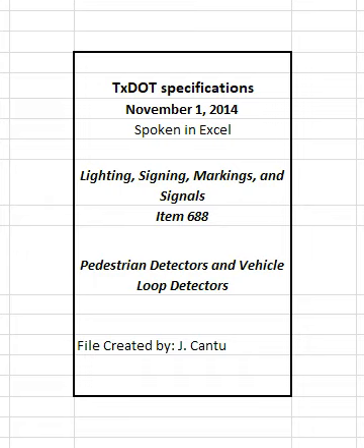Loops installed in multi-lanes will have the same color code in the order the loops are installed. When facing the same direction that traffic flows, the color code will read from right to left for all lanes carrying traffic in that direction. If traffic moves in 2 directions, the color code will be repeated for the other direction of traffic.